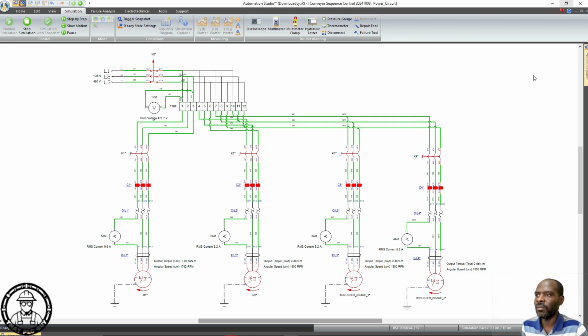Okay, and the best way for you to do this is you've got the actual schematic, the printout, and you've got on that schematic the preset time values. So the only tricky thing, I may say so, is that you need to align the actual observed time in Automation Studio to your expected time, which is the reason why we had to scale the time value so that we just get the expected performance.